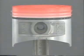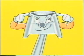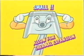The piston head becomes far hotter and therefore expands more than the skirt. To compensate for the difference in thermal expansion, the piston diameter at the head is made smaller than that at the skirt.